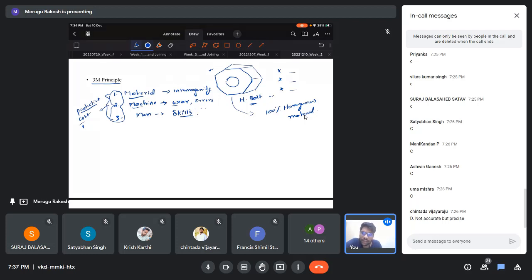So that's why industry people give some tolerance. If I want to produce an 8 mm hexagonal bolt, I will give it some tolerance, say 0.001. So this is the tolerance I will give, the maximum allowance within which the product can be produced.